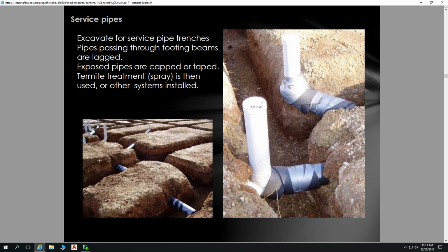It's very difficult to go repairing pipes that are inside a slab. Yes, you can dig up pipes that are in the ground and repair them. Okay, it's annoying, but it's not the end of the world. Repairing stuff inside a slab is bad because you've got to work in from inside. Yes, that lagging should be in place. You can see all this lagging on these pipes before any of the steel has gone down and any of that plastic has gone down.